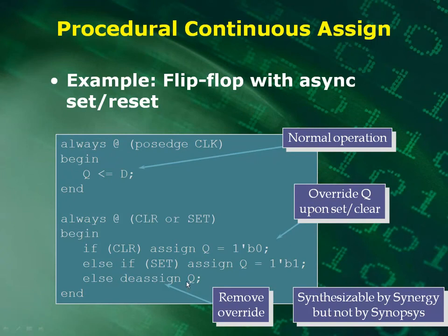Okay. This is not the best way to do things, and I don't recommend doing this because if you're trying to write code that's synthesizable, some Verilog compilers might let you do this, others won't. So again, I don't recommend that when you do things to a particular register like Q that you use different blocks. Keep all your Q assignments in the same block.